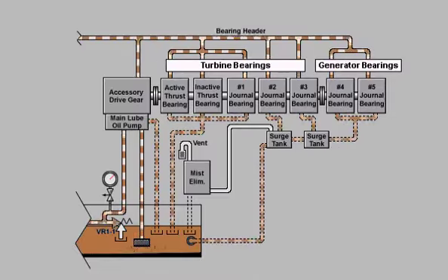The exhaust fan on the mist eliminator draws air from the surge tanks in the turbine base. Oil droplets suspended in the airstream are separated by coalescing filters within the mist eliminator. The mist-free air is vented to atmosphere, and any recovered lube oil drains back into the lube oil tank. To see the flows throughout the entire lube oil system, click on the Show Me button. Otherwise, click on Previous menu.